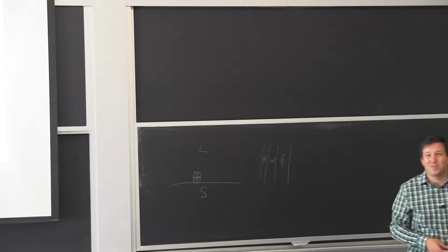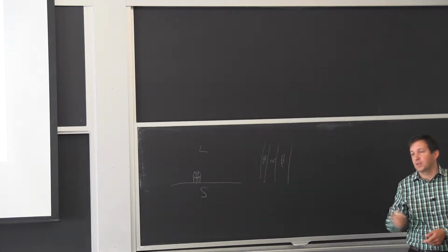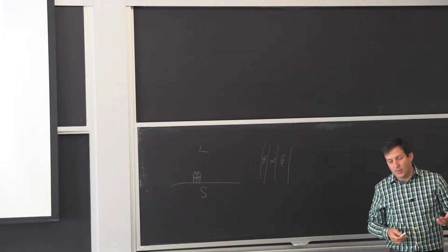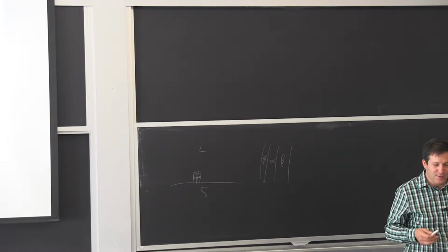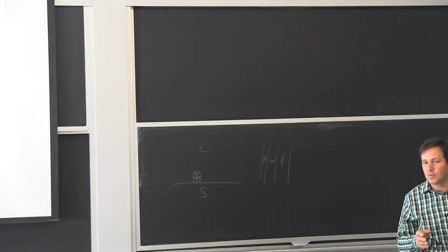You can have a fracture toughness that's only half if the crack goes in the direction of these inclusions as opposed to transverse to it. So all I'm saying is there is still an importance in doing your casting right, but not in terms of the grain size.